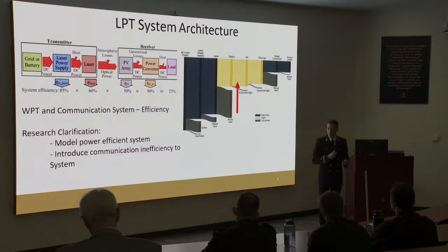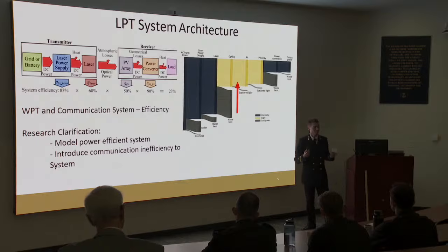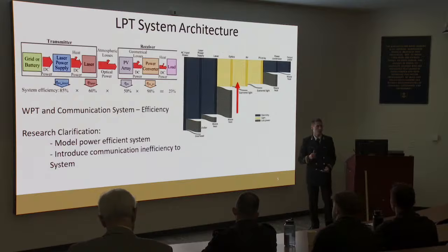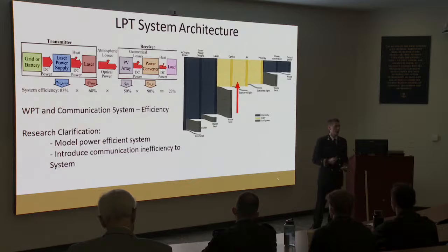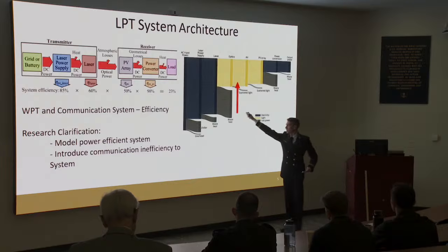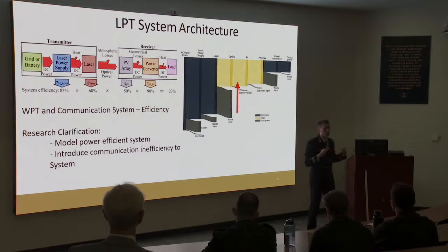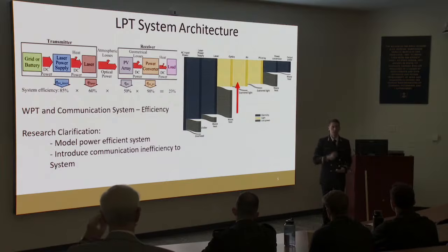Why haven't we seen this before? Well, it's because LPT systems, like I said, suffered from end-to-end inefficiencies. And intentionally modulating your laser diode decreases the power transmission that you're sending, essentially adding another level of inefficiency. If you see right here at this red arrow, this is where we're adding an additional inefficiency to the system. However, because the system is finally mature, we can intentionally add this to the system and still be commercially viable for both commercial and military applications.